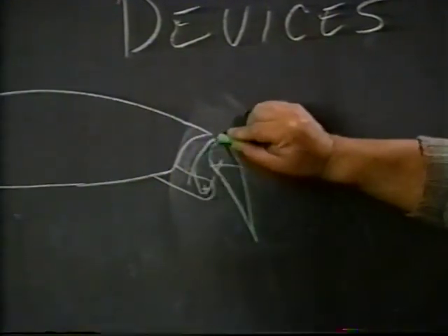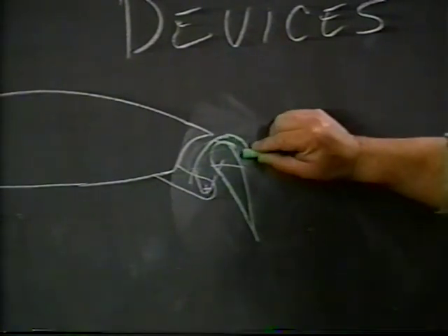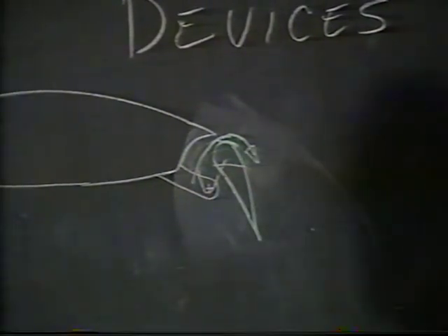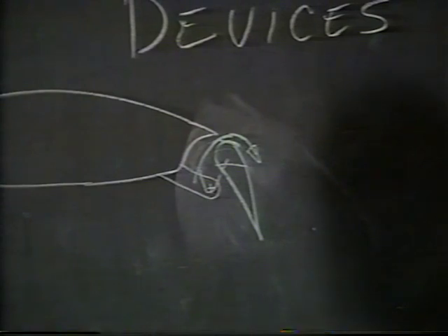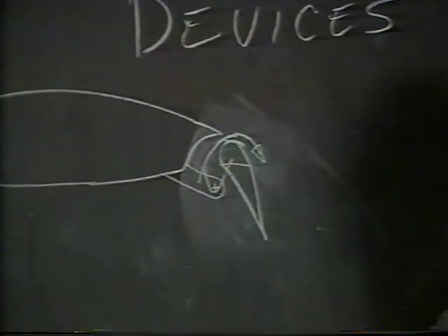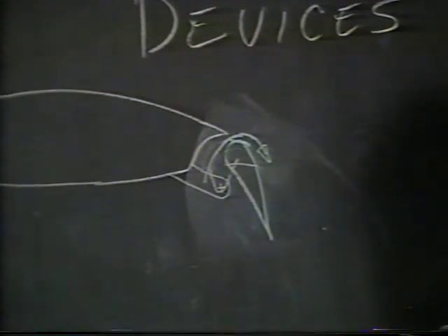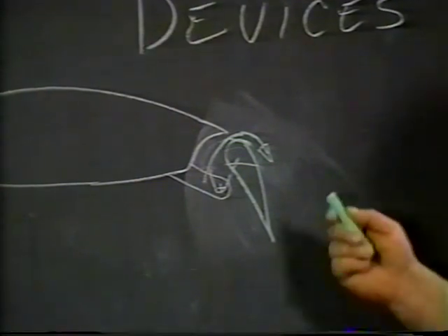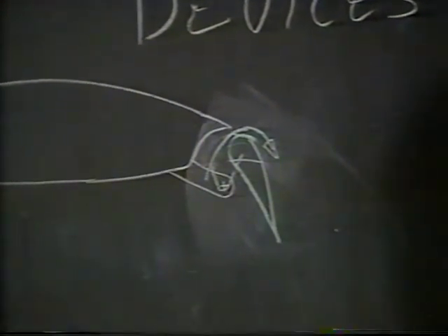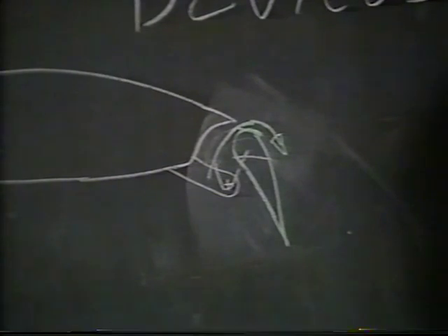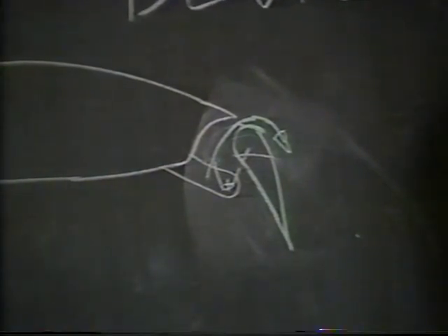It comes around through the slot and really becomes almost a boundary layer control device on the flap section itself and produces considerably higher lift than the normal split or plain flap would do. The slotted flap here is a very common flap, a very good flap, a very effective flap.